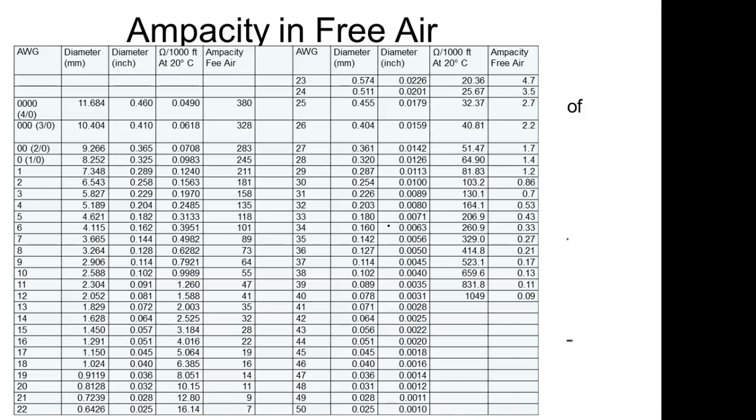So what the National Electrical Code has done is derate these things. Derate means degrees by. They basically bring it to the worst case scenario. So if I run 14 gauge wire inside a house and use the ampacity listed by the NEC, it should meet every situation I could possibly think of, right?